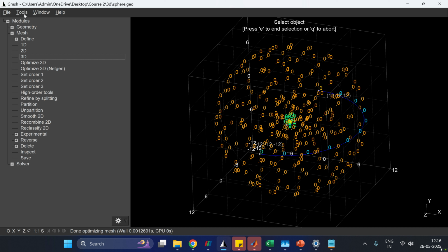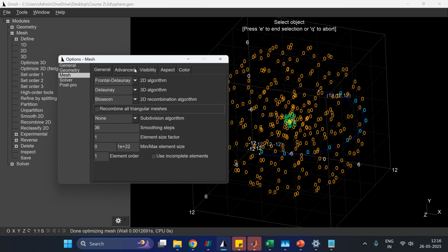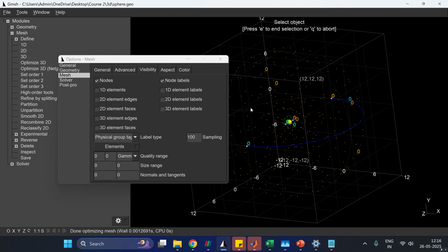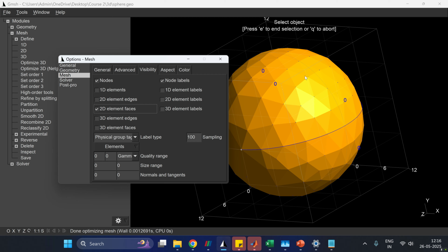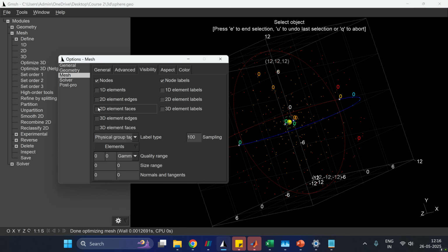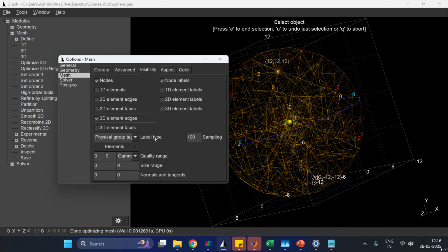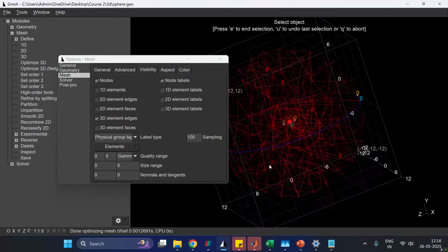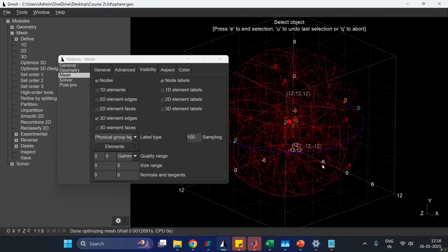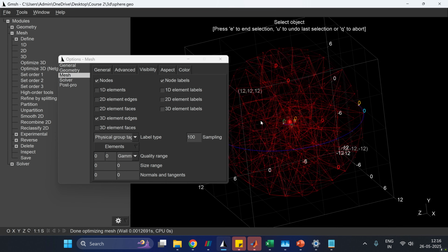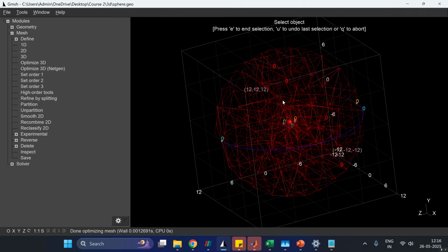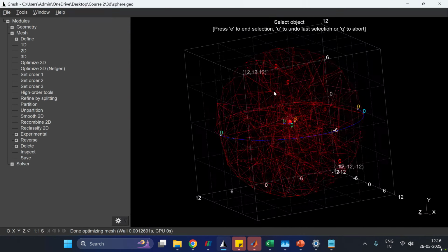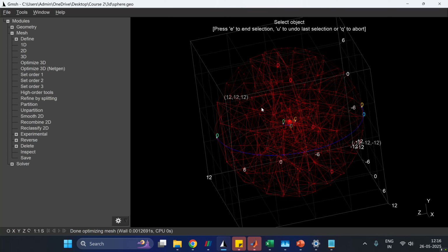So this has created the 3D mesh. All right, so this is our 3D mesh, and let us have a look at it. These are your outer elements, your outer triangles, and this is your inner, right? You can see there are these nice tetrahedrons inside. So this is our mesh, and now of course we'll have to refine it a bit, but first let's just do this on a coarse mesh.